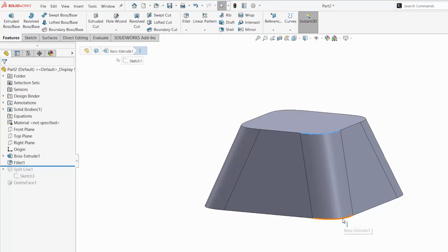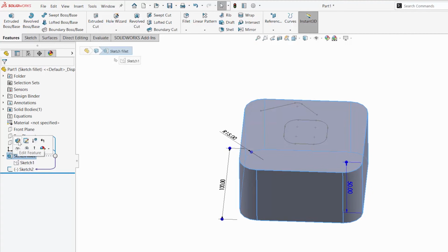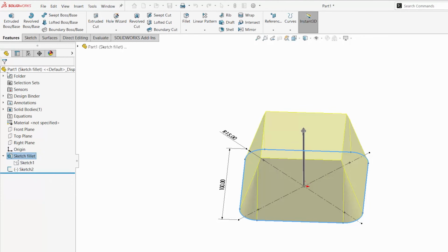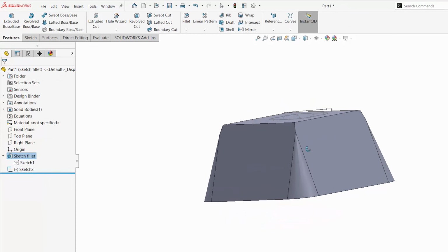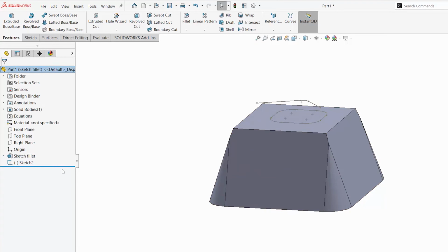And you'll notice that the fillet arc length is the same at the top as it is at the bottom, because it's a feature fillet, it builds that in. Now, watch what happens when we do this to a sketch fillet. When we add the draft, it's going to draft this profile all the way up. If 19 degrees isn't enough, you'll see that our fillet is actually going to terminate. So it meets up at that triangular point.